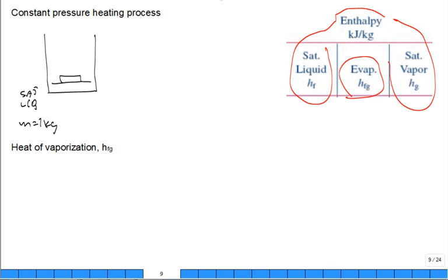And you bring some heat into the system, Q. During the process, you're bringing in heat until the end of the process. I still have the mass of 1 kilogram because it's a closed system. The mass hasn't changed. There's my system. I'm focusing on that trapped amount of water, that 1 kilogram of water, but it's now all saturated vapor. Okay? The weight of the piston didn't change. Did the pressure of the water change during that heating process?